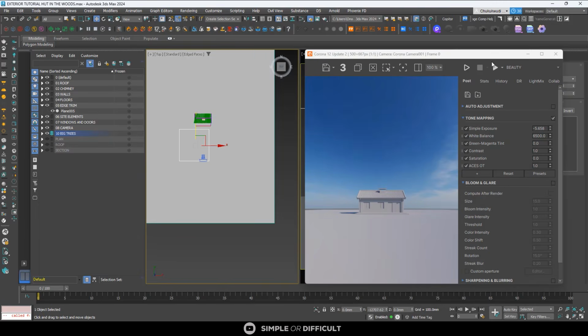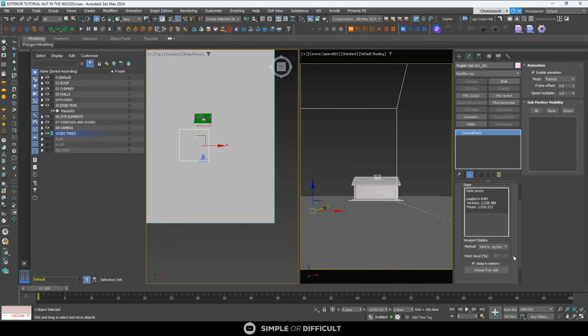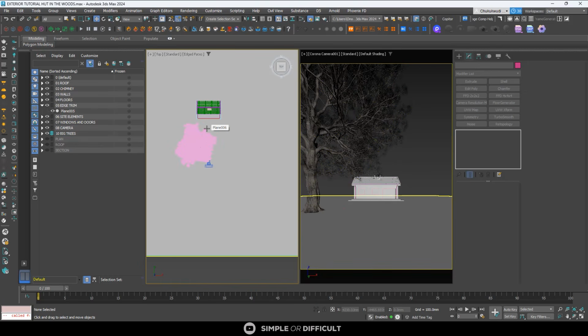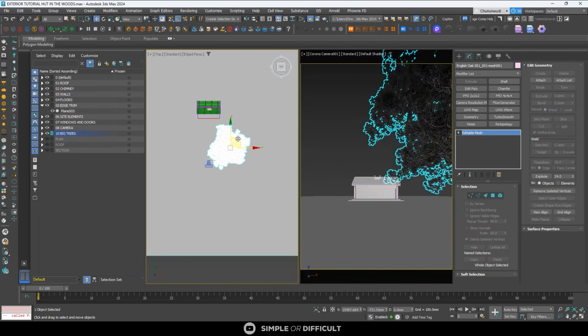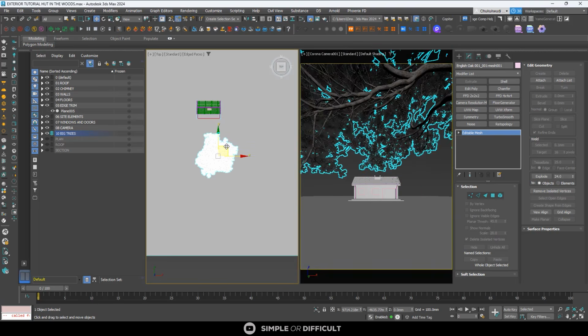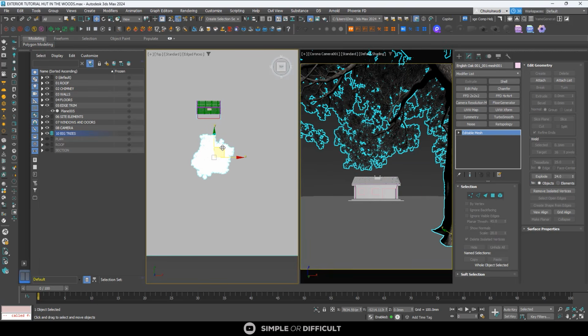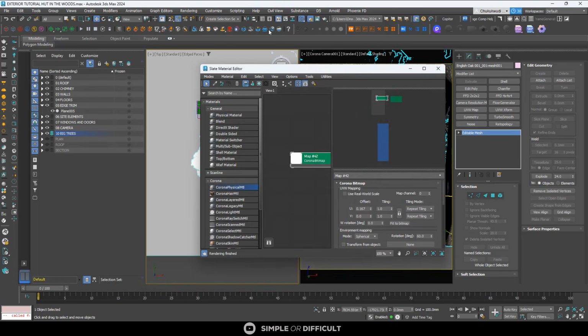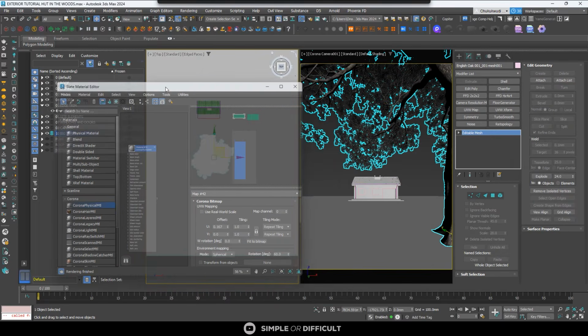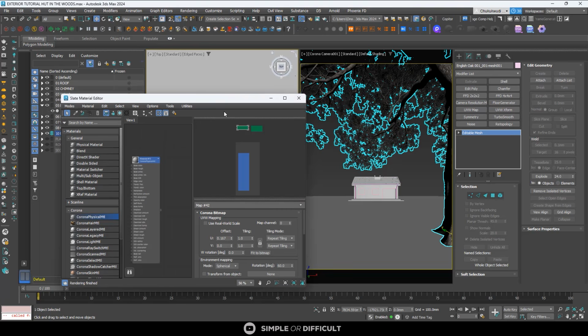So what I'm going to do, let me minimize this for now, is come down here and then duplicate to mesh. When I do that, I'm going to delete this first one. Now, what I want to do is material override. I want to override the materials, right? So that we can actually focus on the shadow and light composition. Then later, when the time comes, we're going to work with this material, this tree.